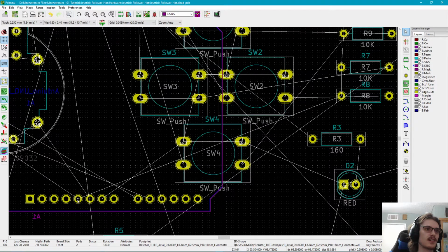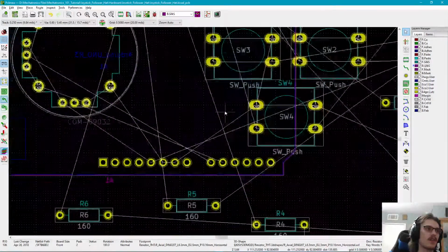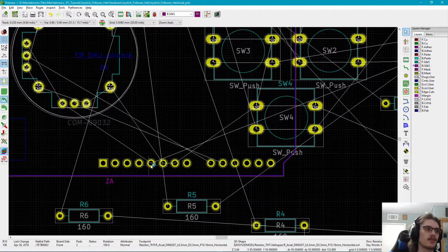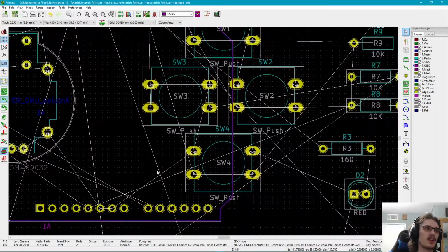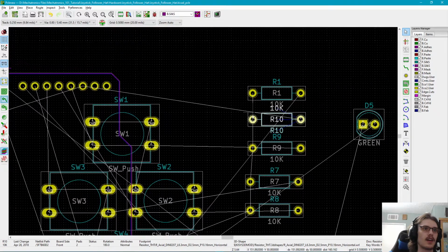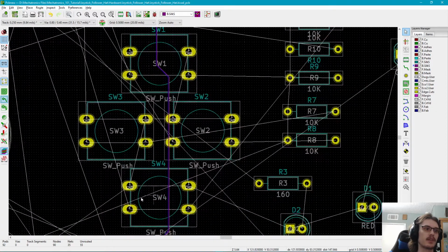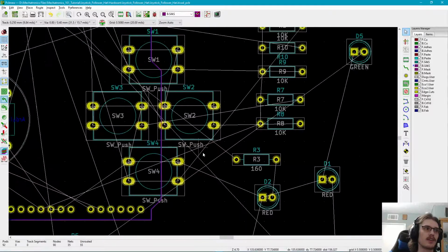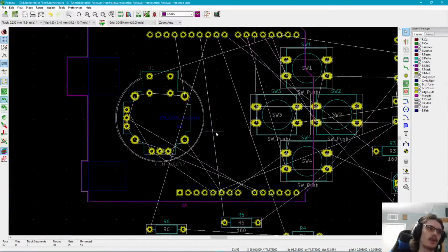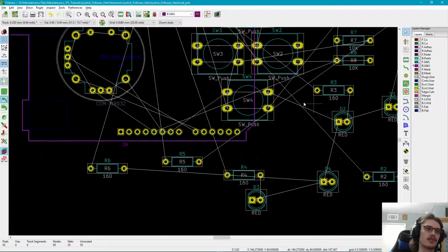If you connect this via to this via, instead of having them all connect specifically to this via where all the wires go here, what you could do is kind of daisy chain it, where we have a connection from here to here to here to here to here and back to here, and they would all still be in parallel because of how the PCB works. And in fact, we're going to be doing that when we set those up. So that's why these are a little more flexible and we can kind of push those off to the side.